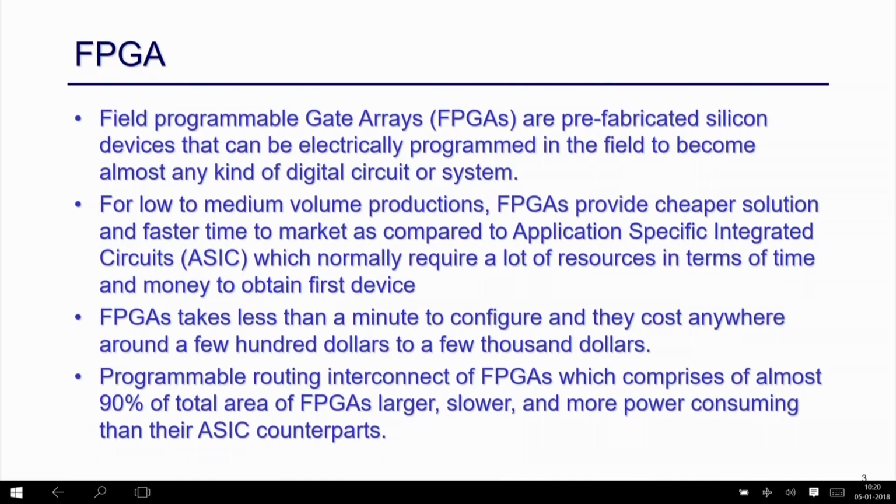The disadvantage of FPGA is that it's a little bit slow because it has programmable interconnection, so it has all the possibilities built in. So it is slow, also power consuming, and also larger compared to the ASIC design. So for a given design, an ASIC design will be much smaller than an FPGA design. But because of the other advantages, FPGA is widely used in EDA industries.